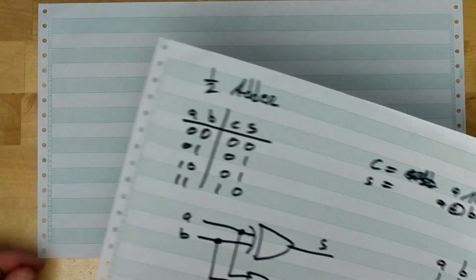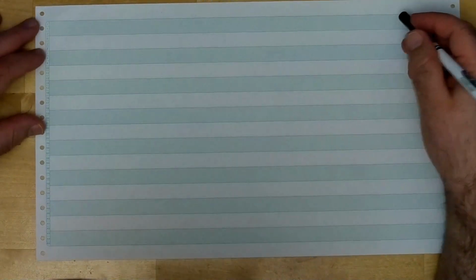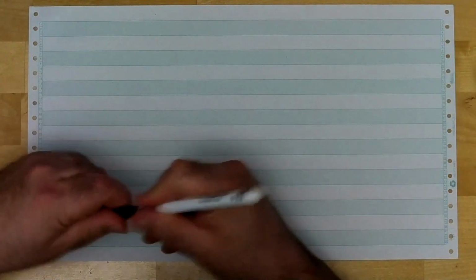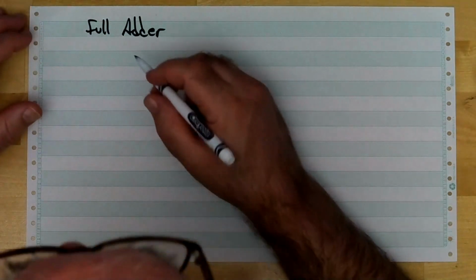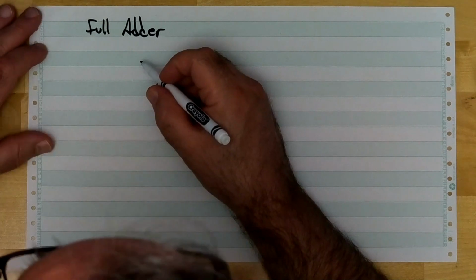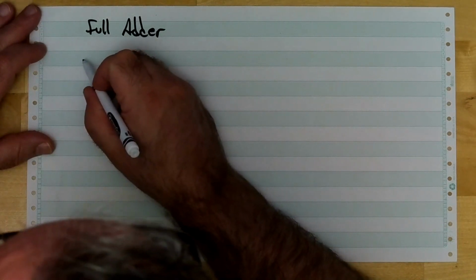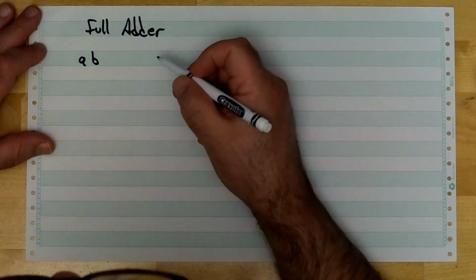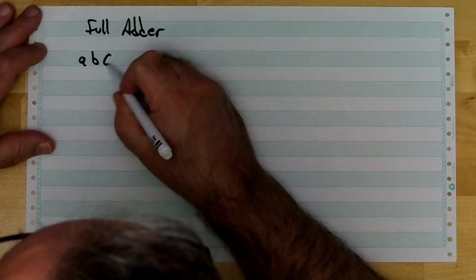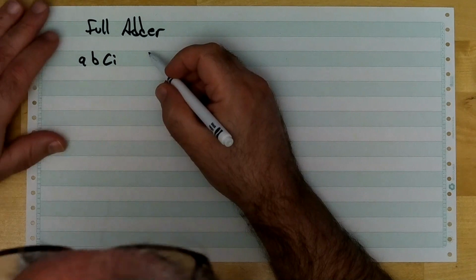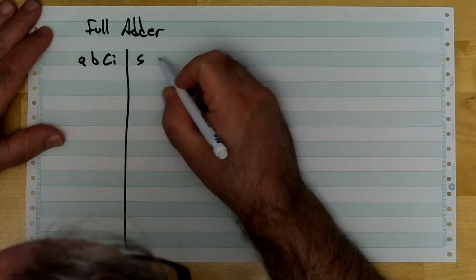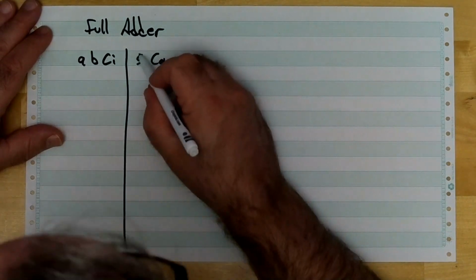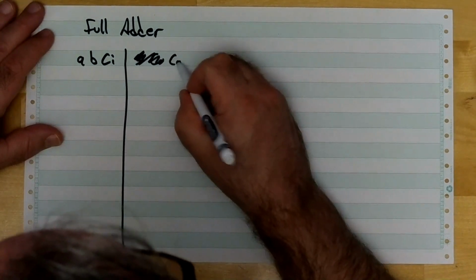What then is the other kind of adder? So if that's a half adder, is there a whole adder? Well, no. Well, yes and no, although it's not called a whole one. It's called a full adder. Now let's start by looking at what the truth table looks like for that thing. What we're going to look at in a full adder is we're going to have an A input and a B input, just like before. But we're also going to have a carry input. Then we're going to have a sum and a carry output. You know what? When I draw these, I like to have the carry output on the left.